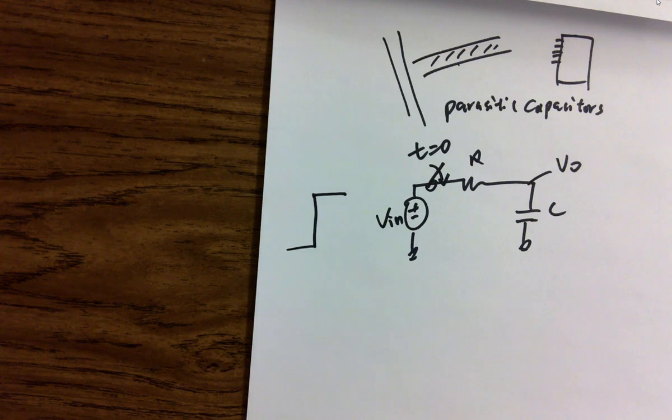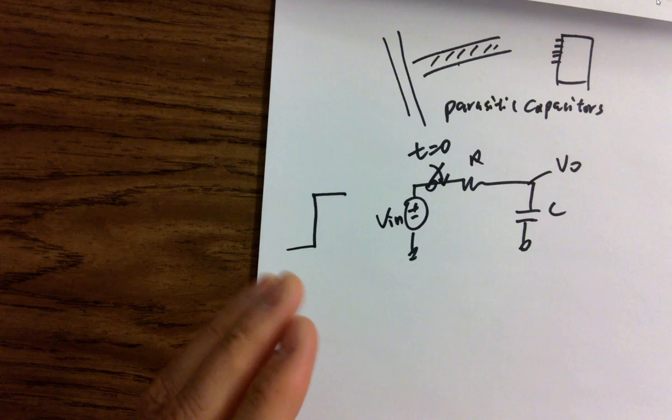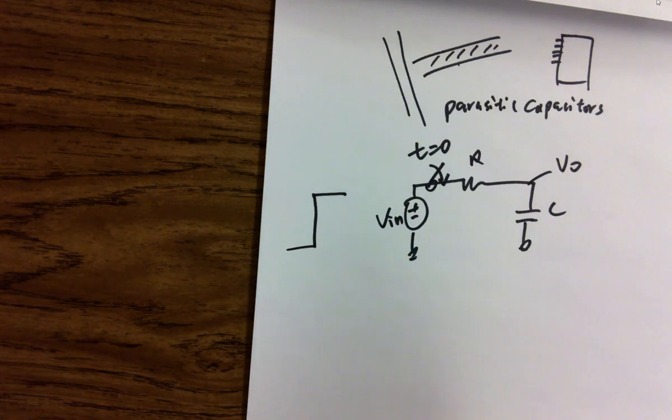And you have like 0.5 millimeter here. You want the pulse to reach these 2 points at the same time. So it's having issues. They have different distance, which means different resistance, and will give you a different time delay actually. So you have to insert buffers to delay this shorter one to make it longer.